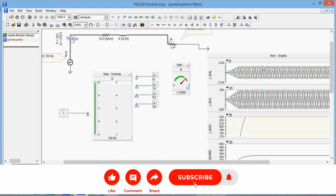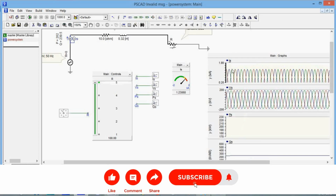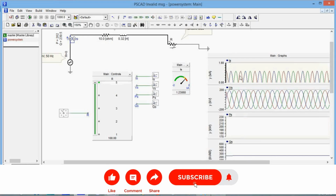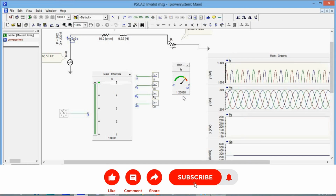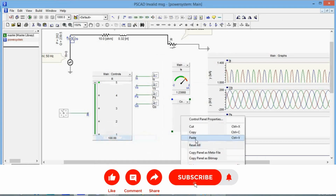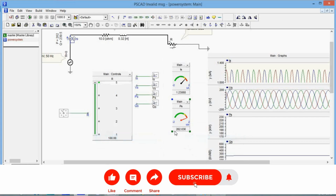We are not able to find the exact value from the sinusoidal. Here we can assume that the exact value is 1.23. Now if we want to see the active power, go to graphs, meter and control, add as meter. Just right click it and paste it. This is 262.36.